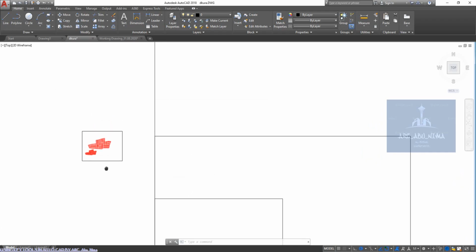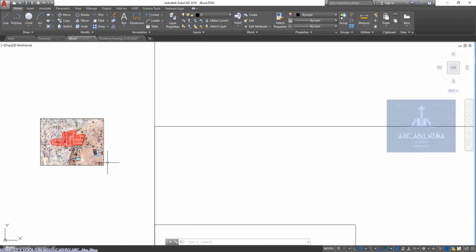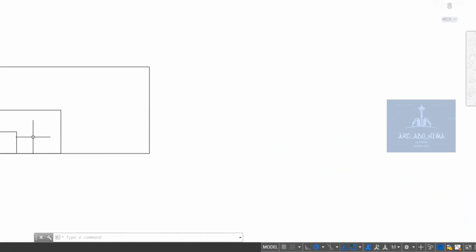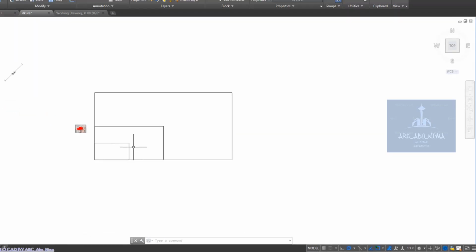It's very easy for you to snap the drawing. Once you know one particular distance on the drawing, you will be able to scale it to reference. Maybe you have a drawing you want to work on in 3D, so you can simply bring it to AutoCAD, scale it, then export it to your 3D software for 3D drawings.